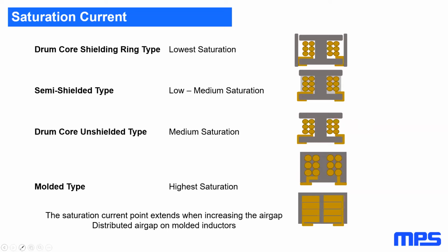All right, and then next up we had: to reduce the parasitic capacitance in layout, can you cut out the local ground plane under the inductor without risking significantly higher chances of radiated emissions? Yes, and this is exactly what is covered in that webinar. On the MPS website, look for EMC, layout, inductor tricks. You have exactly this kind of scenario, and I remember because I saw it recently. I highly recommend checking that webinar from monolithicpower.com. I think you will find these answers and more tips for design layout.